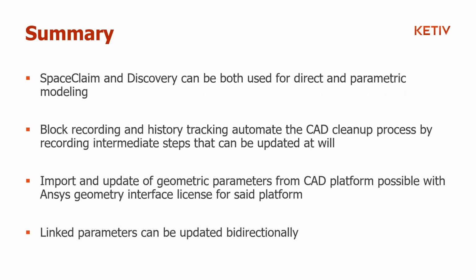And we also saw that some of the parameters that were imported maintain the link between your native CAD design and your SpaceClaim design. This bidirectionality is limited. So any modifications that you make inside SpaceClaim itself will not be carried over to your native CAD platform.